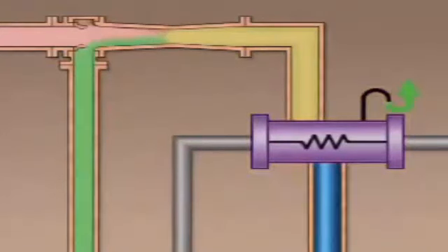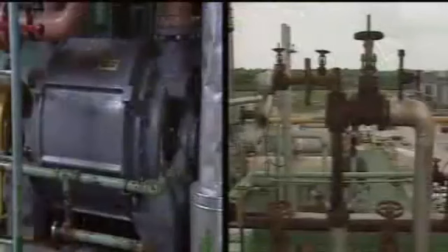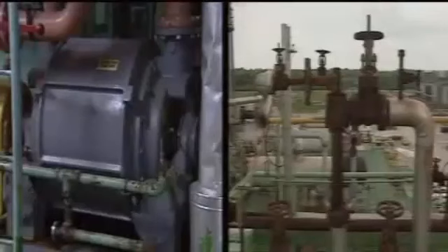Vacuum pumps and air ejectors can be used in various system configurations to remove air from a condenser. For instance, some plants use a combination of a rotary pump and an air ejector because it allows a large volume of air to be removed from the condenser. Other plants use 2 or more air ejectors connected in series.